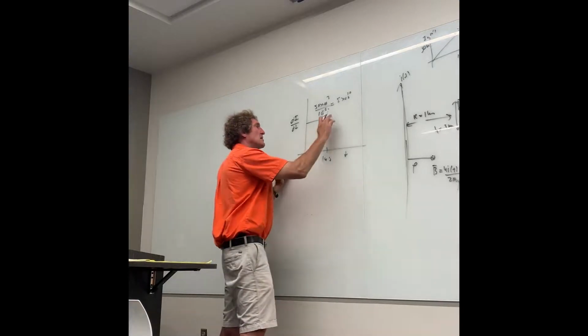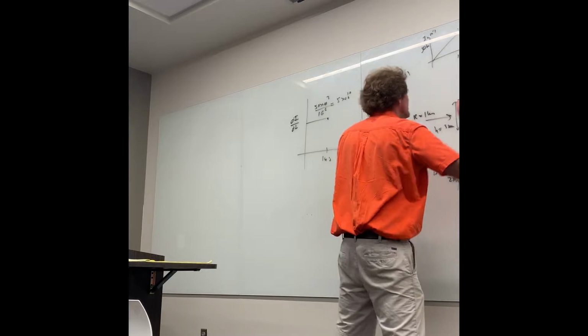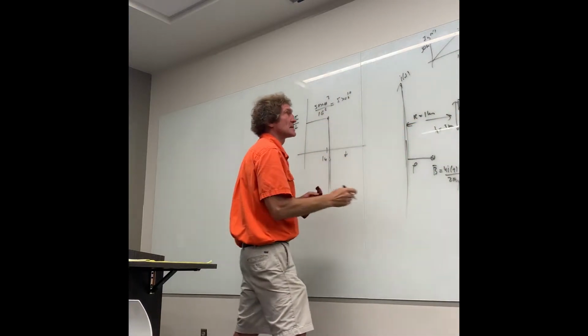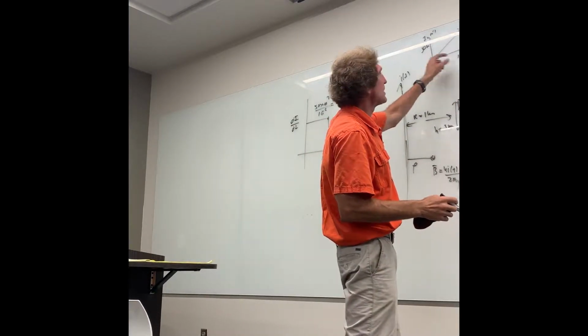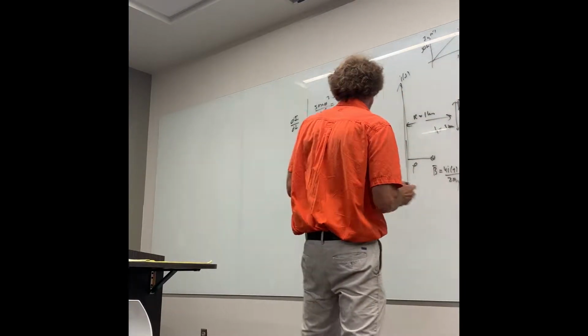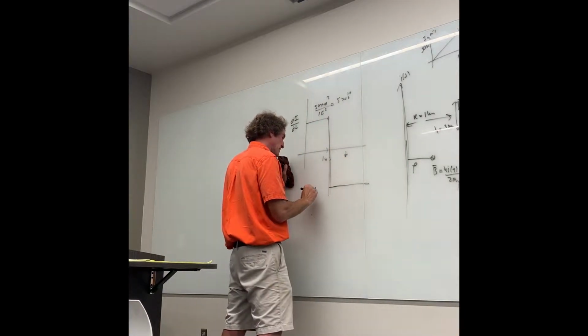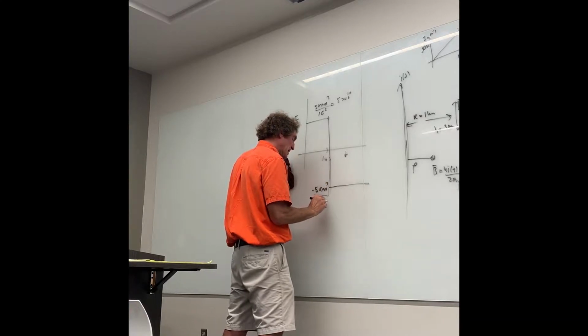That's where it's going to be out to 1 microsecond, and then it's going to invert the polarity, and it's going to go down because now the slope's negative, and it goes from 50 kiloamps to 0 in 9 microseconds. So this is going to be minus 50 times 10 to the third over 9 times 10 to the minus 6.